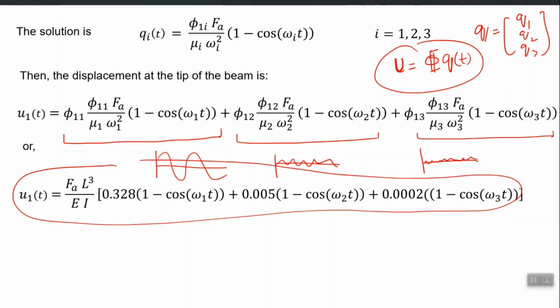So principally now you can handle any multiple degree of freedom system if you are given its m and k matrix, right? Because that is what is required to first calculate the mode shapes and time periods, and that will become the starting point of your modal RHA.